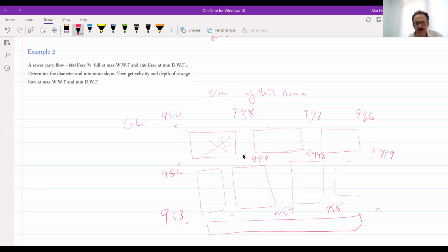This is first of all. So what should we do? Firstly, you have to start putting the manholes at each interconnection point, at each corner. So for example, here we should put the manholes. Okay, now we have these manholes. So how many manholes do we have? You have to number the manholes.